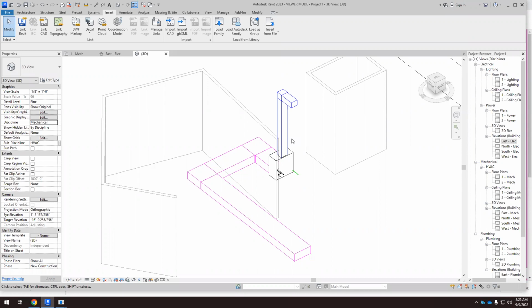Yeah, but if we place the column there, then you have to do a thicker slab, because the span is larger. So designing, it's always something that you have to go back and forth. If you don't know anything about structures, if you don't know anything about systems, you will suffer a lot, because when you get the project back from those structural and mechanical engineers, you will have to make a lot of changes.